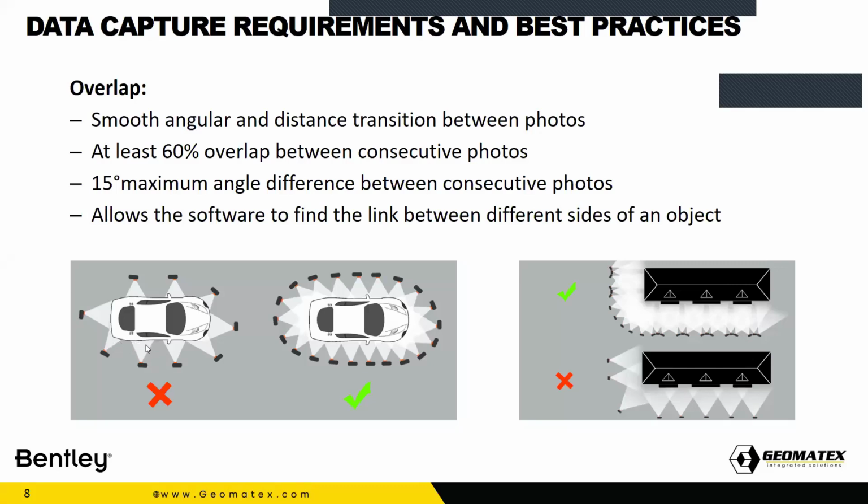Those are just some single photos. But here, when I decreased the space between different photos, I successfully got an overlap. Maybe this overlap is just a theoretical example, but it's not enough because we should get more than 60 to 80% to be able to do a reality model.